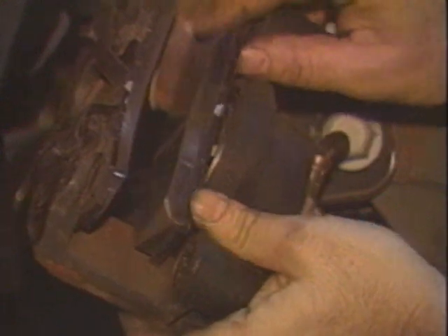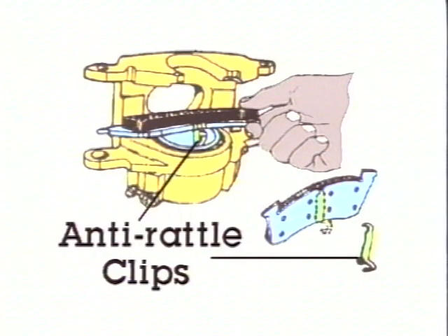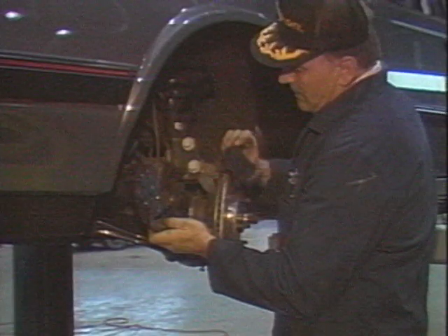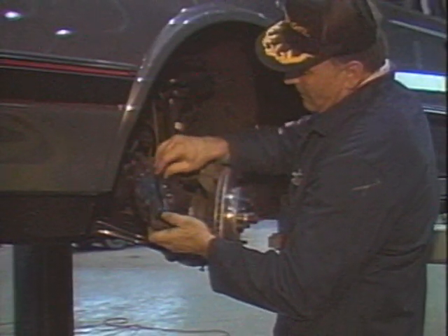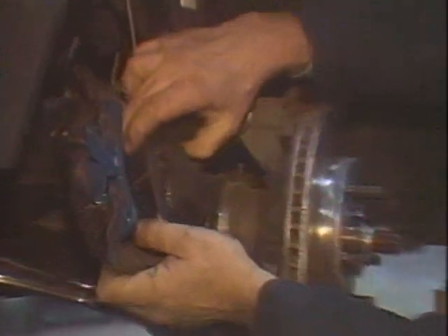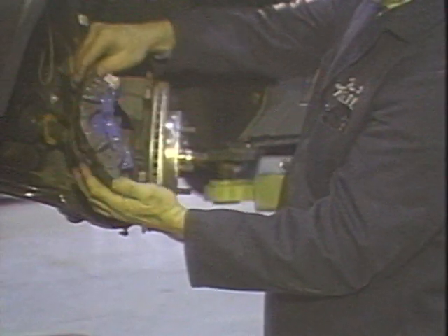After installing the disc, fit the new pads into the caliper. Make sure all anti-rattle clips are installed correctly. If the clips are badly rusted or weakened, use new ones. Keep oil and grease off the pad lining material or the new pads can become glazed and squeal.